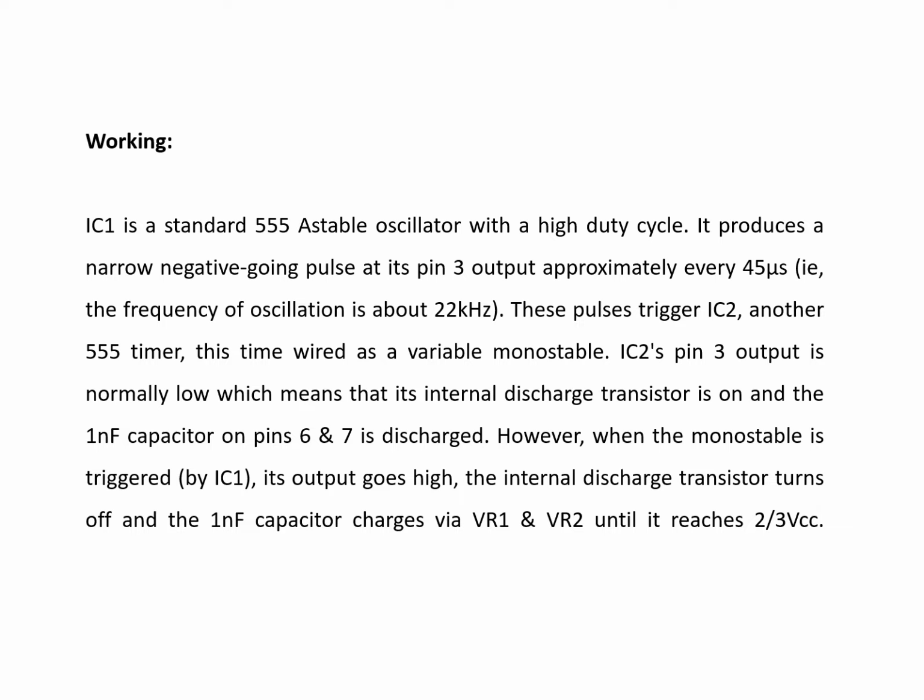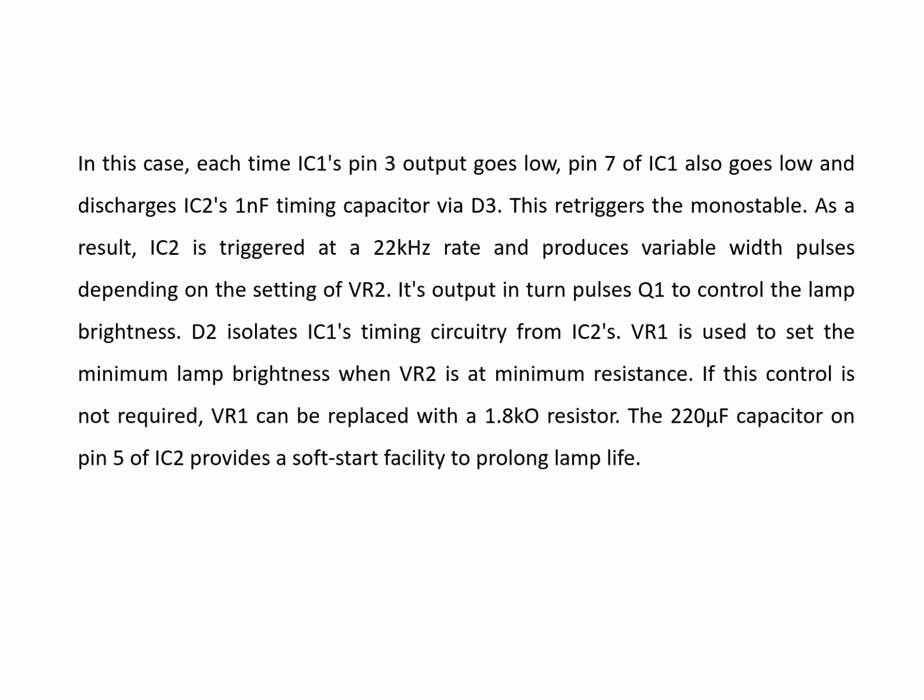Okay, so the advantages: it provides soft start protection for halogen lamps, reduces filament inrush current, and extends lamp lifespan. High efficiency due to MOSFET switching. That's what I have said already. Adjustable brightness using PWM and stable operation with regulated power supply.